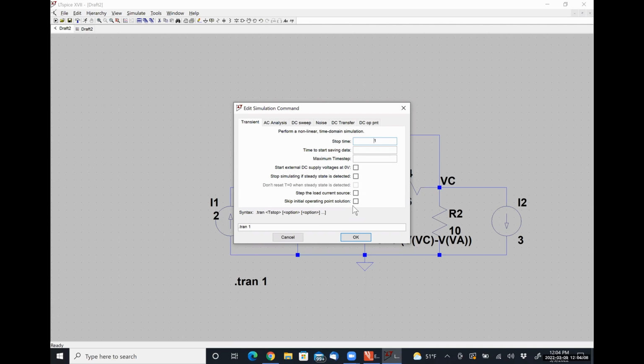But when we're doing transient analysis of RL, RC, and RLC circuits, telling it when to stop is important because we are trying to look for changes. So if we had a circuit that had a time constant of, let's say, 1 millisecond, and we looked at it over a time span of 5 seconds, we wouldn't really see any of the transient behavior because it would occur so quickly that we wouldn't catch it. So our best bet would be to look at it only for a time of, say, 5 to 10 milliseconds so that we can actually see what's happening. But we'll talk more about that when we start looking at circuits that aren't DC, which will be Friday.